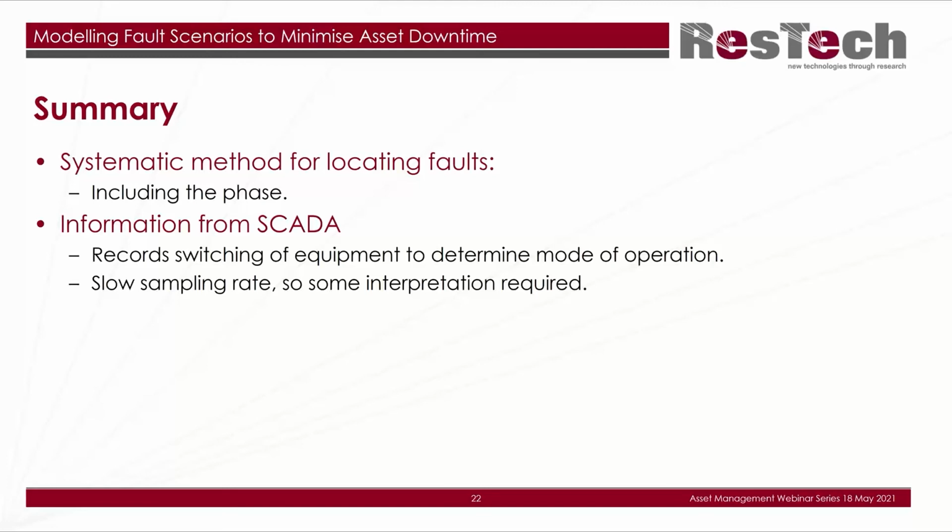Now, of course, the SCADA would give us things like when devices are switching and what actually has tripped, which is good. However, the only thing that is a little bit difficult sometimes, and may require some interpretation, is the voltage and current waveforms, where whilst we see a nice transient happening there, we might only find that we only have like 2 or 3 data points. But nevertheless, it still ends up being a way of matching up that to that.